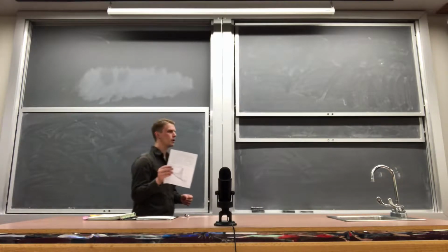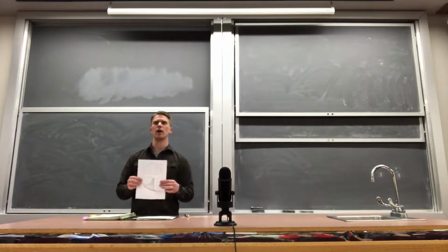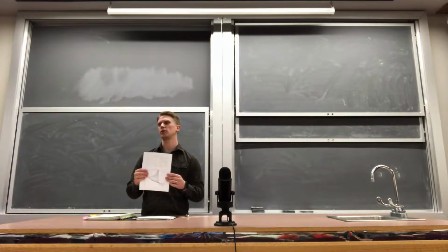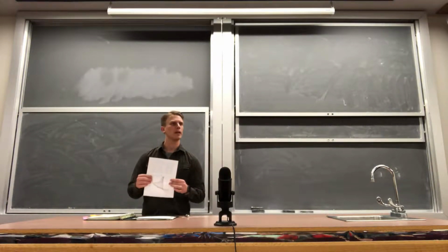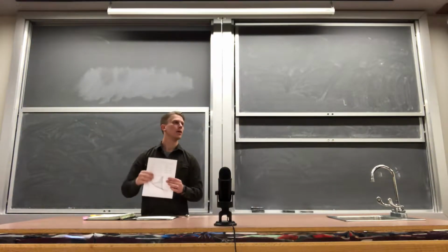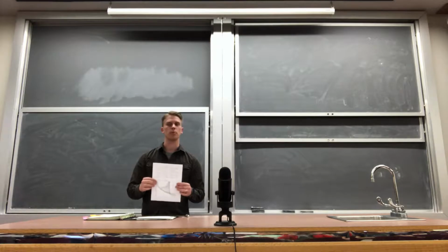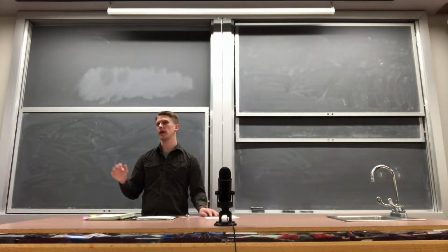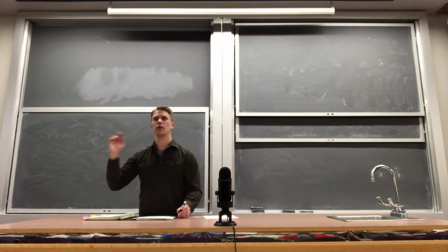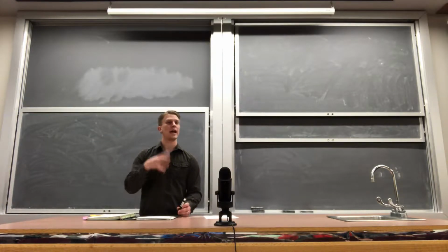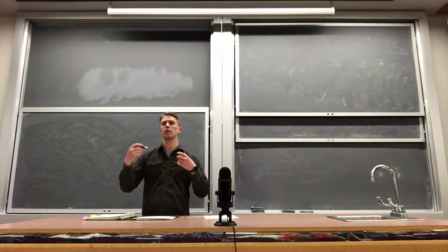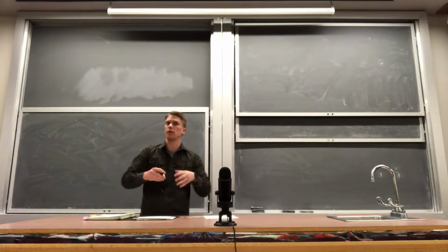So the goal of what we're trying to accomplish here is that I don't want to make the problem seem sort of trivial and sort of arbitrary. Right? I want to make the problem seem less arbitrary. Instead of saying it's 10% coming out of the top, I want to use thermodynamics to predict what is the amount coming out of the top, for example. And then I don't say, oh, it leaves at 30 degrees Celsius. I want you to calculate what temperature it leaves at. Right? So we're adding in some complexity, but the material balance component is going to be the same.